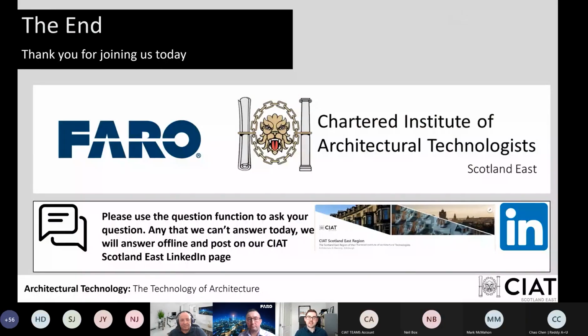In terms of the on-site application, you're preparing to go to a building. You've got this building to scan. You may be doing an internal retrofit, or a conversion or a change of use or something like that. So step one, go and get some asset information and you scan that. I remember back in the day, you had to go and get a bunch of checkerboards or targets and pin them around the place. And then whenever you got it into a piece of software like Scene, you would use those checkerboards or those balls on tripods so that you could manually register everything together.